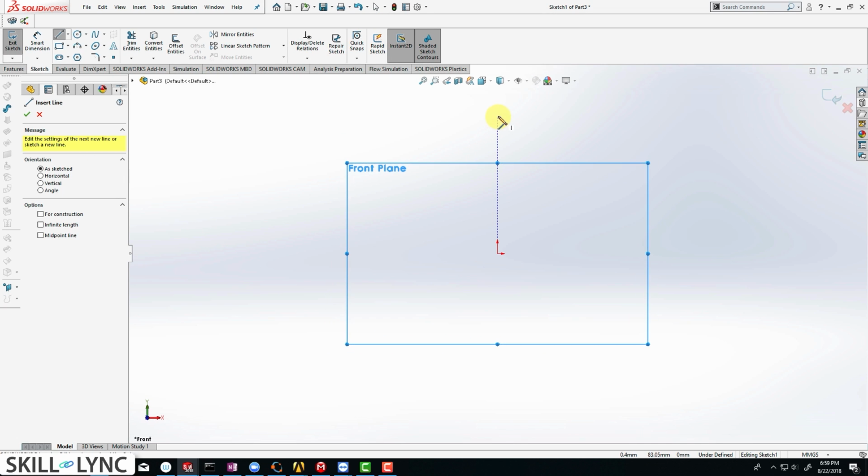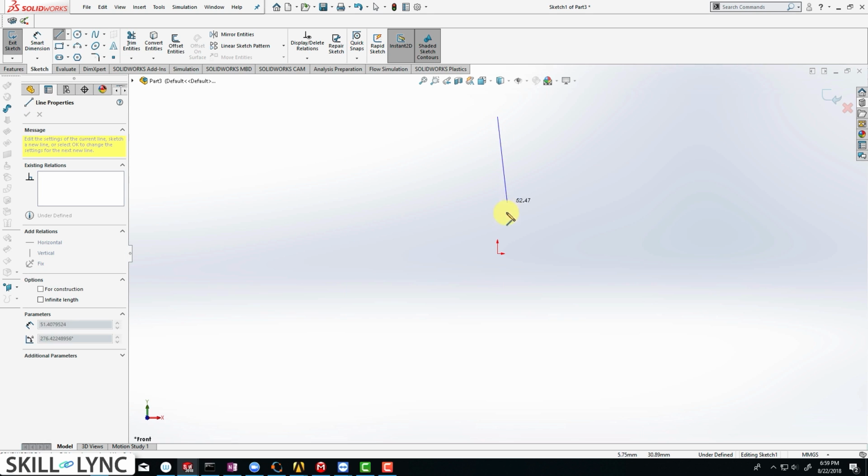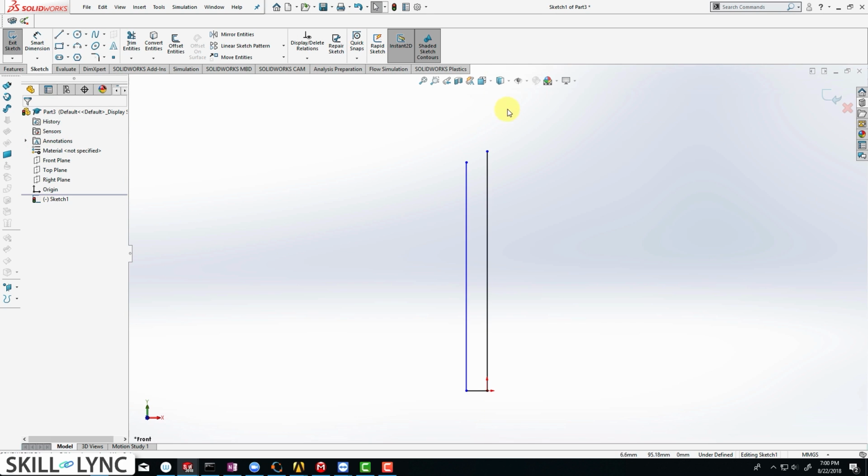So here we are going to get started by drawing a few lines. Use the line tool and just click here and then just drag it out. Try to make that coincident with the y-axis and make it coincident with the origin, and then let's drag it out to the left, drag it again to the top, and that basically looks okay. Hit escape when you're done.